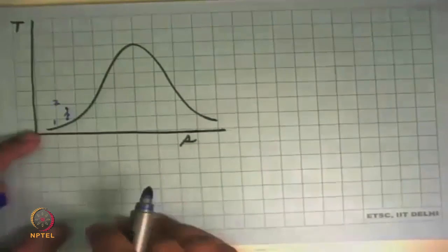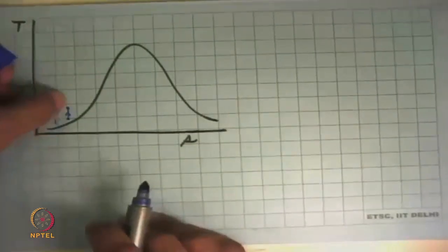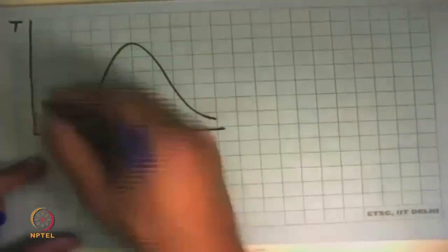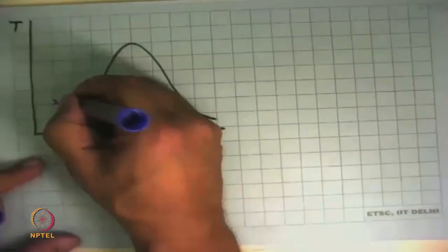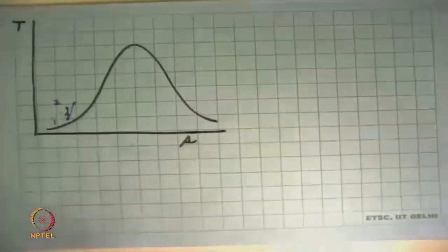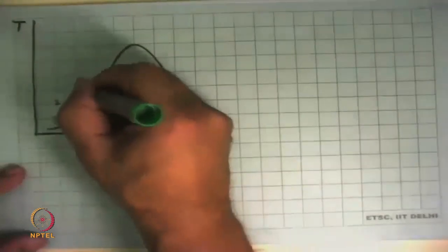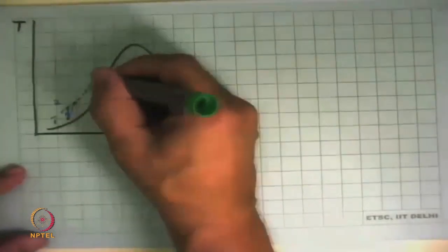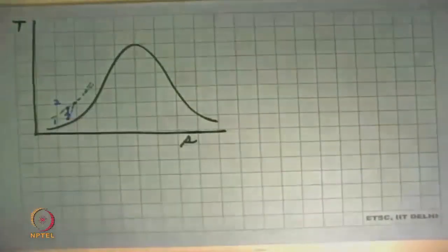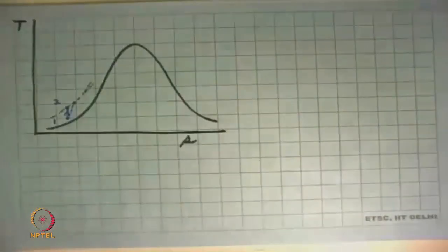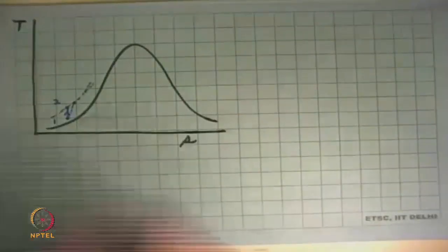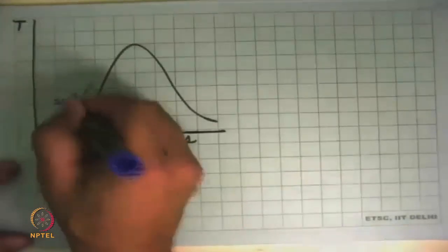This is isentropic compression in the ideal case. It has gone from there to there. The real compression will go to the same pressure. Isobars are like that. So the discharge pressure isobar goes somewhere there. But it is extremely close to this line, so it's very difficult to differentiate that. This is the isentropic case. This is the real case.